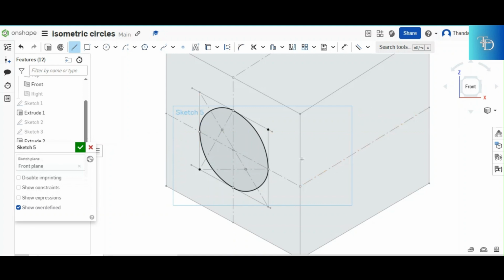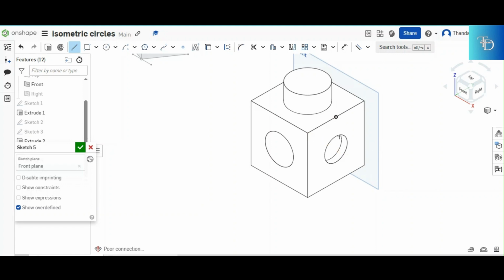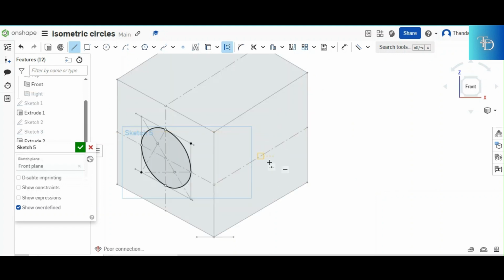So now let's go over and deal with the one that is at the right hand side. Now it's time for us to deal with what? With the right hand side, which has that kind of a hole right there. So what we need to do is to recreate that kind of a hole. Same thing applies. We use the diameter 50 to create that hole right there. Now when we come to this side, there are basically 2 circles right there. We have a hole which is represented by the circle that's on the surface, and then we have another circle inside because now we have depth.